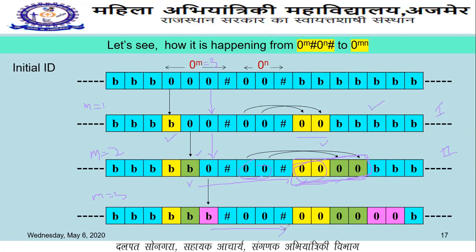Okay, and this time again we copy this multiplier after, okay, to this partial product. This is our previous partial product which came from the previous step, second. Okay, now this we copy after this partial product like this. Okay, so this 0 is copied like this, and second 0 is copied like this. So this is our step third.